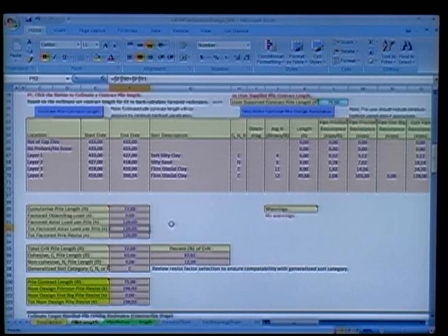We got exactly 128 kips because the spreadsheet iterates and interpolates and does all that better than we do, and so it comes out perfect at 72.66. Well, then you start first checking, okay, am I actually cohesive like I assumed? It figures that out for you, and it says you got 87.6% cohesive, so definitely this is a cohesive pile or a cohesive soil category. And if it wasn't, you would have to go back, look at what you put in for your resistance factors up above and change them if it came out different.